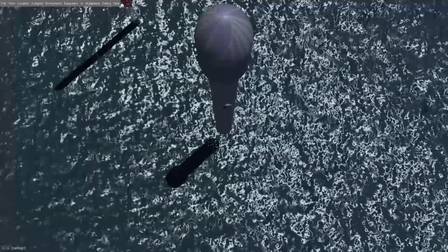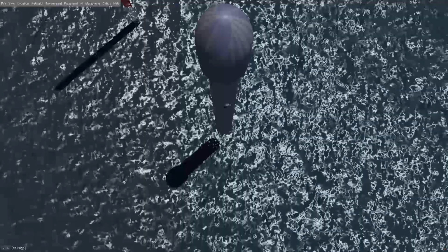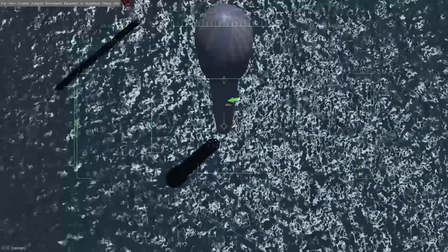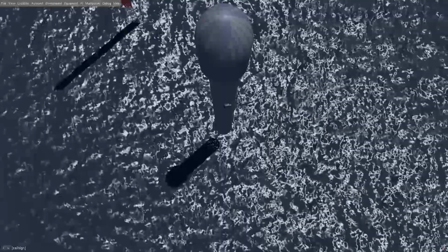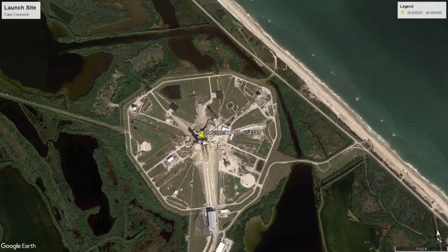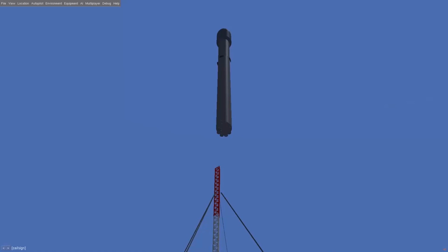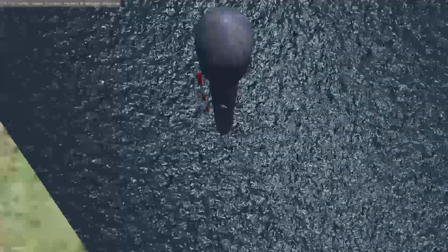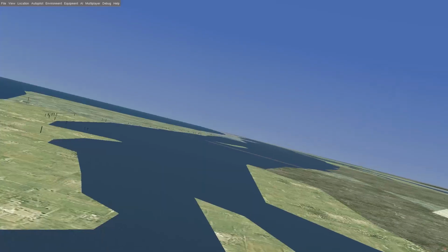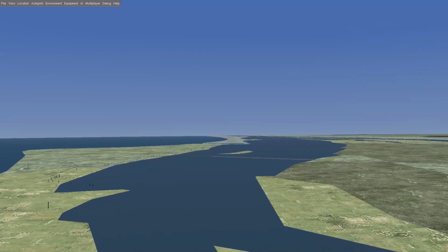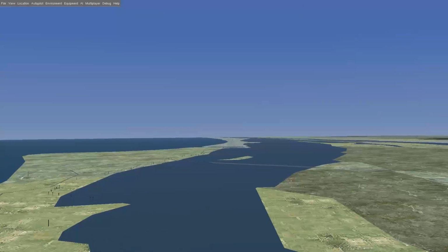And if you look at the simulation in FlightGear, so that's the Cape Canaveral launch site. I mean, it's not the exact coordinates, so it's sea there, but it'll actually be land if you look at the real place on Google Earth. So we have the launch there. Initially it'll go up straight, and after about half a minute we will initiate the gravity turn. That is why I put the step command there, as you saw, for gamma in and T time, the turn time.